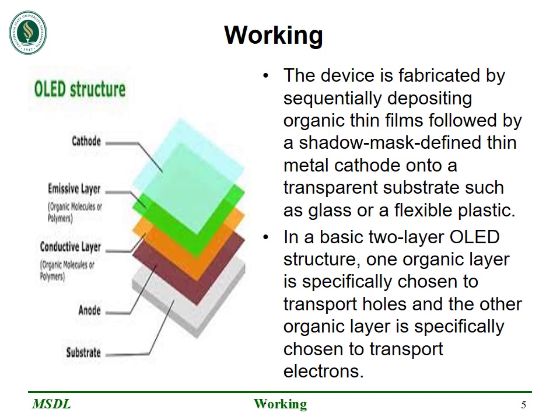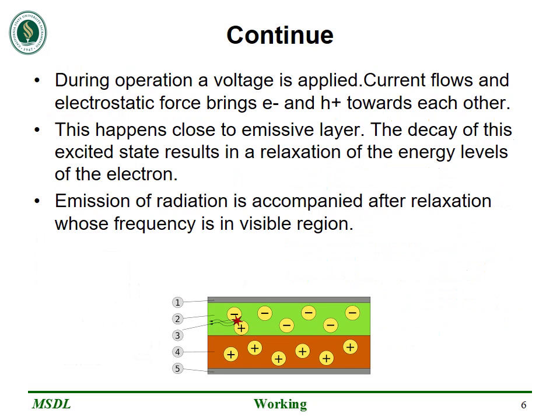During the operation, a voltage is applied across the OLED such that the anode is positive with respect to the cathode. I couldn't find a better figure than this, but I guess you can work it out. Anodes are picked basically upon the quality of their optical transparency, electrical conductivity and chemical stability.